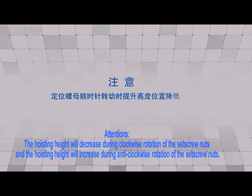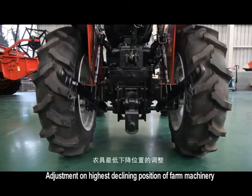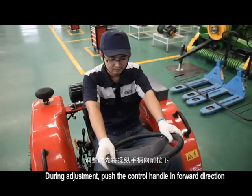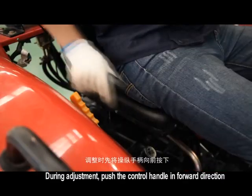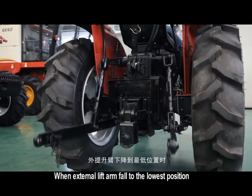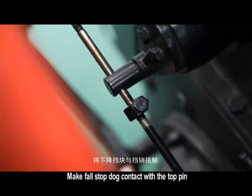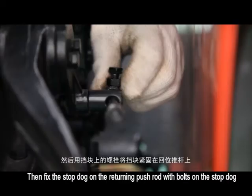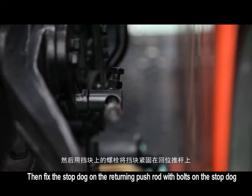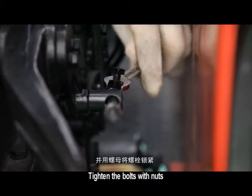Attention! The hoisting height will decrease during clockwise rotation of the set screw nuts and the hoisting height will increase during anti-clockwise rotation of the set screw nuts. Adjustment on lowest declining position of farm machinery. During adjustment, push the control handle in forward direction. When external lift arm falls to the lowest position, make fall stop dog contact with the stop pin. Then fix the stop dog on the returning push rod with bolts on the stop dog. Tighten the bolts with nuts.